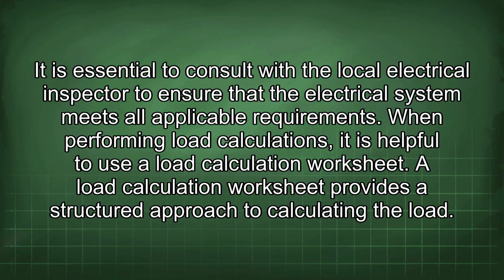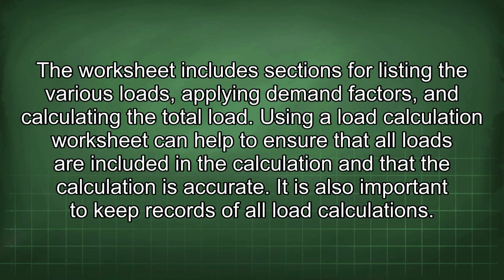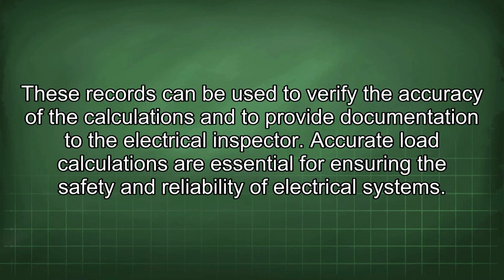When performing load calculations, it is helpful to use a load calculation worksheet. A load calculation worksheet provides a structured approach to calculating the load. The worksheet includes sections for listing the various loads, applying demand factors, and calculating the total load. Using a load calculation worksheet can help to ensure that all loads are included in a calculation and that the calculation is accurate. It is also important to keep records of all load calculations. These records can be used to verify the accuracy of the calculations and to provide documentation to the electrical inspector.